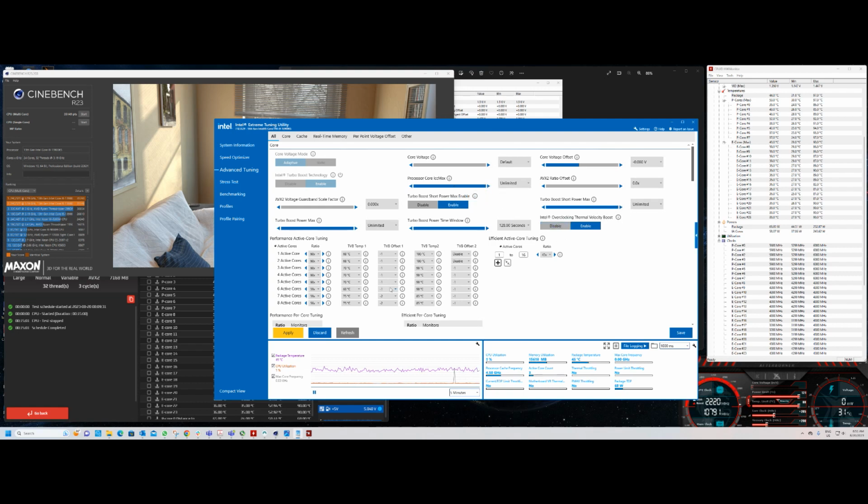The one difference is that by default, you're probably going to see Intel Overclocking Thermal Velocity Boost disabled. In my configuration, you have the option to enable it. Of course, you don't have to, but this actually worked, and I found that my temperatures were able to stay under 100 degrees Celsius thanks to the Thermal Velocity Boost.